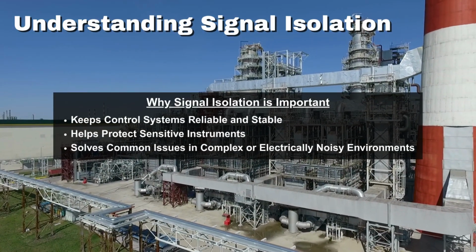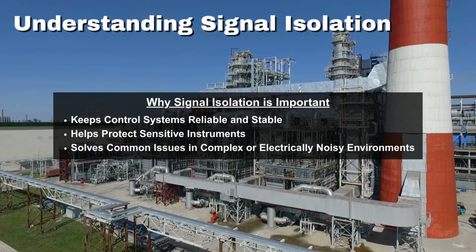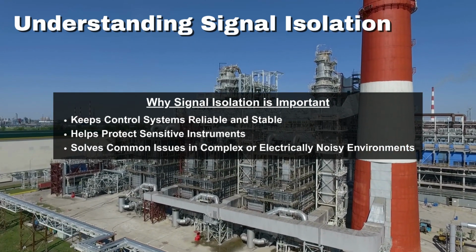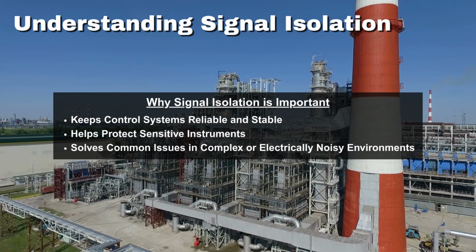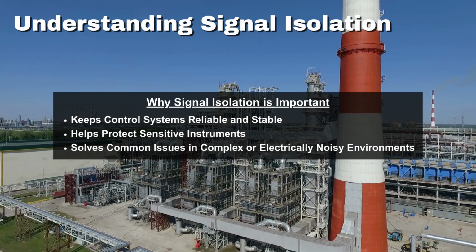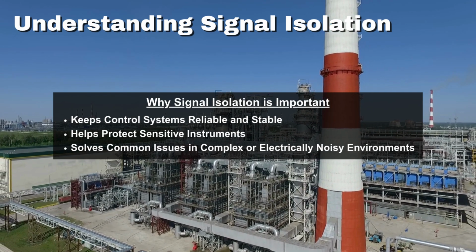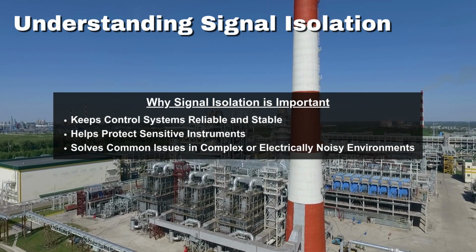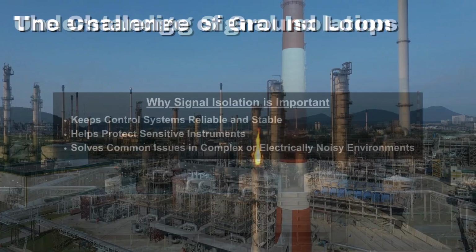Signal isolation became especially important when electronic transmitters replaced pneumatic transmitters. New electrical challenges such as plant noise and problematic grounding scenarios, which were not issues with pneumatic infrastructures, were introduced into measurement circuits. One of these common problems, the ground loop, continues to be a challenge today.